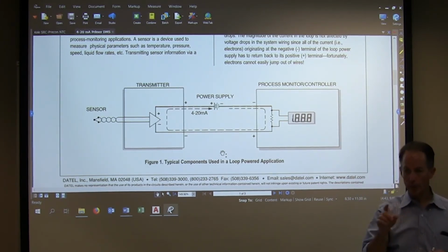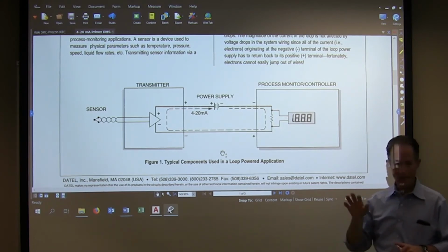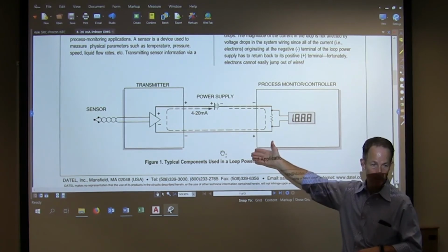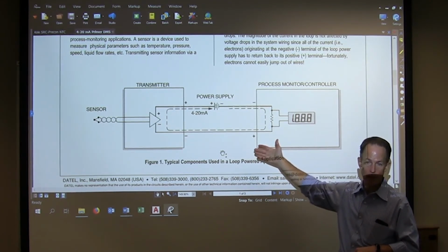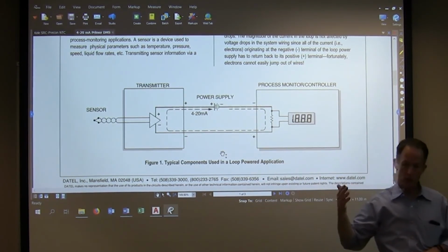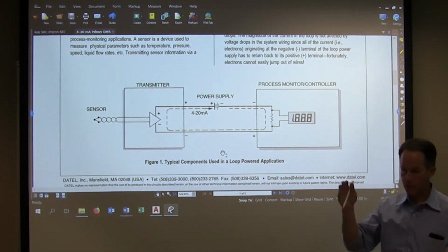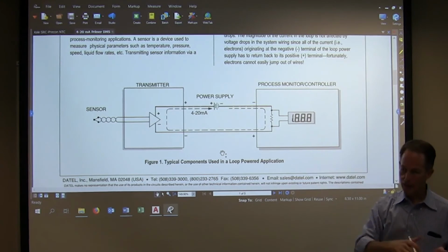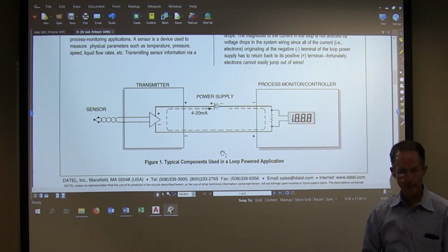Okay. So if you're troubleshooting this, can you just troubleshoot the 4 milliamp portion of the signal? No, you've got to do the top end. The top end's probably more critical, but usually, if you're going to run it through the range of low to high, you want to make sure to get the top end and then make sure it ramps between the two. Okay.